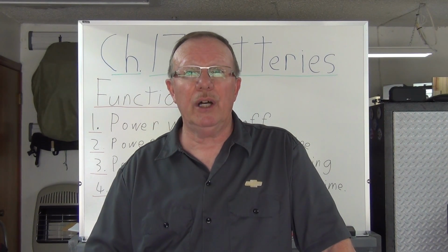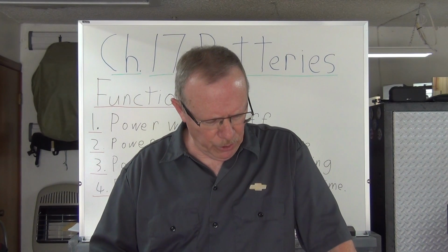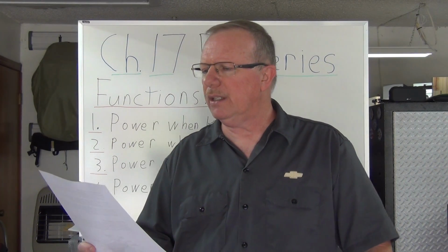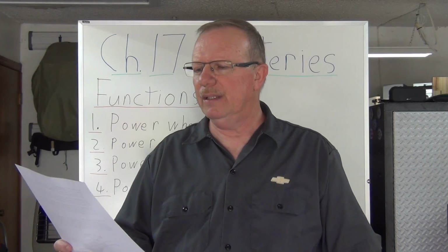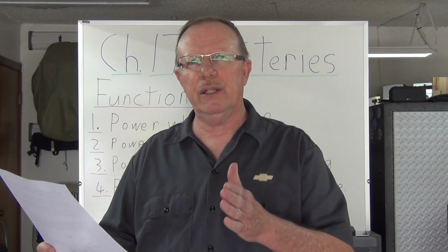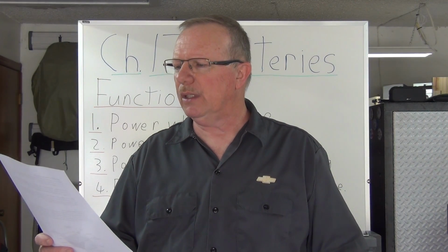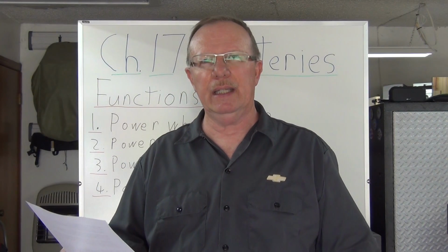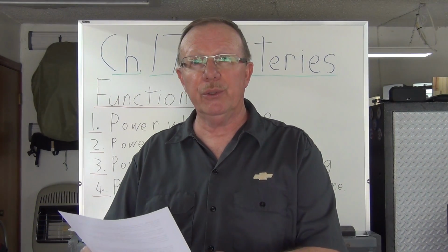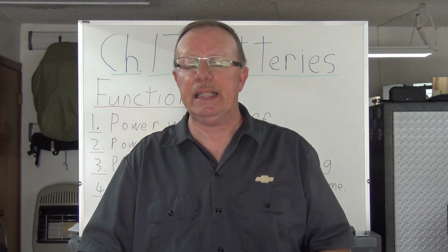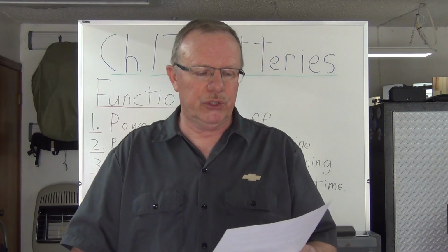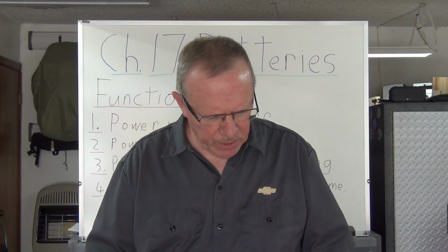All right, battery construction next on page 3 here. We're still on, and it's on page 236 in your book. An automobile battery contains a diluted sulfuric acid electrolyte in positive and negative electrodes, okay, in the form of several plates. These are made into plates, and there's a pretty good little picture there of what those look like. Since the plates are made of lead and/or lead derivative materials, this type of battery is often called then that lead acid battery. The battery is separated into cells, and in the case of automobile batteries, there's 6 cells, okay? And each cell has several battery elements, all bathed in an electrolyte solution. Okay, so we have positive and negative plates in an electrolyte solution. Okay, so let me look here.